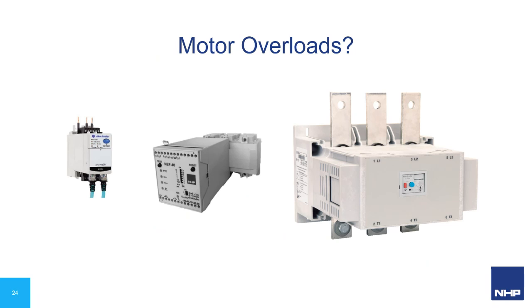This may be caused by lower starting torque of the motor, not allowing acceleration to reduce the locked rotor current, not allowing the load to get away. In other words, stalling during the load's run up, and this can cause excessive currents to go through the thermal overload and cause a thermal overload trip. The inrush current does not cause a thermal overload trip.